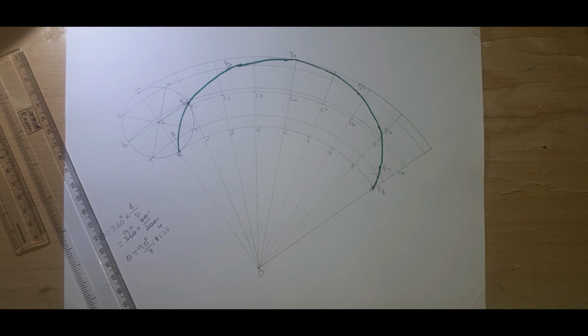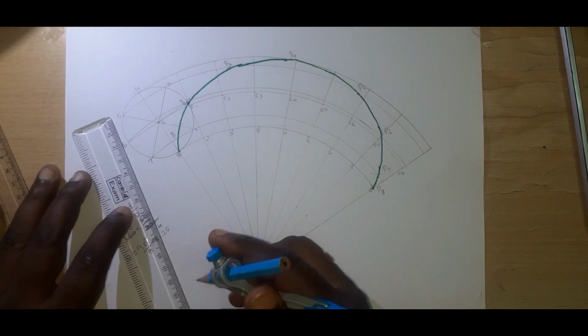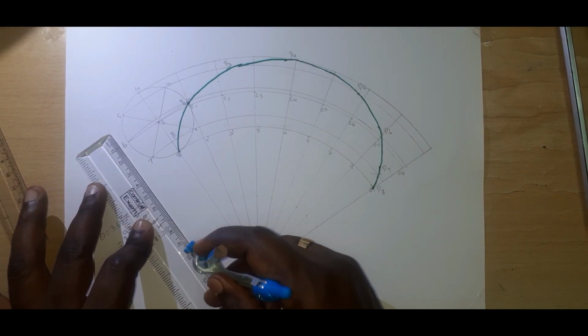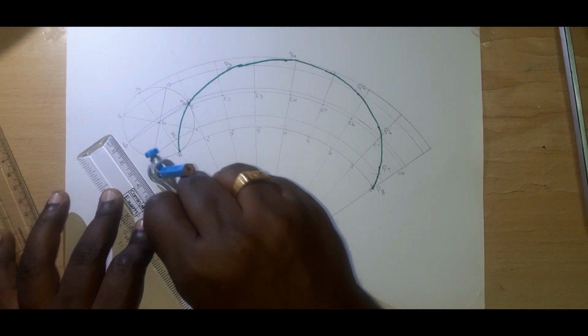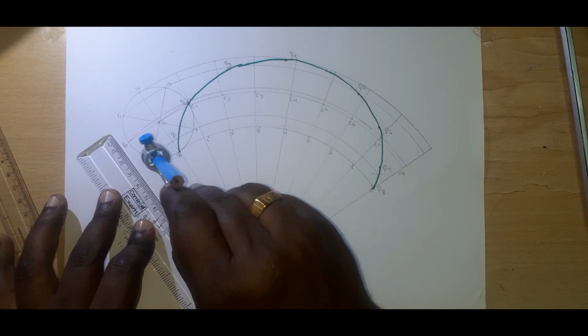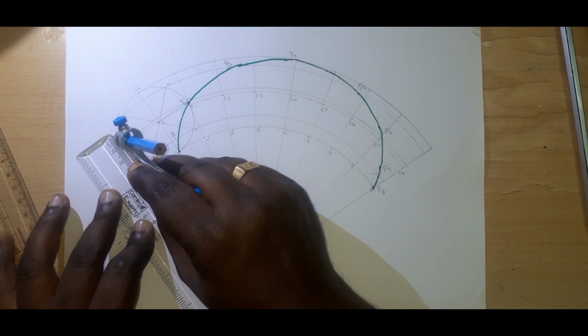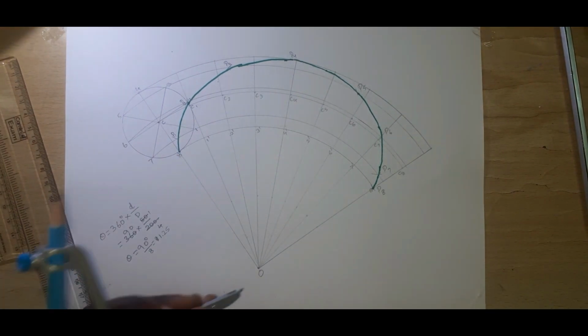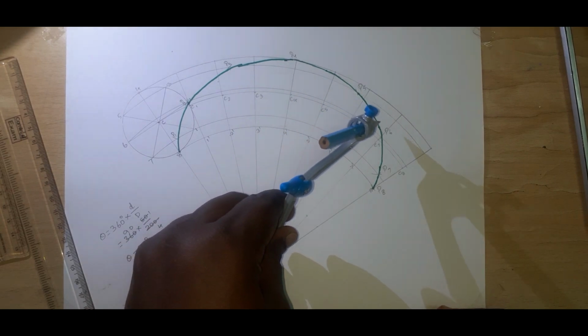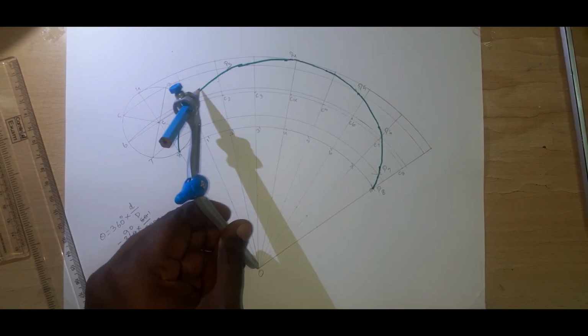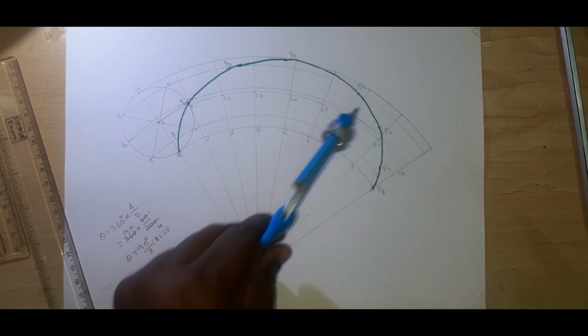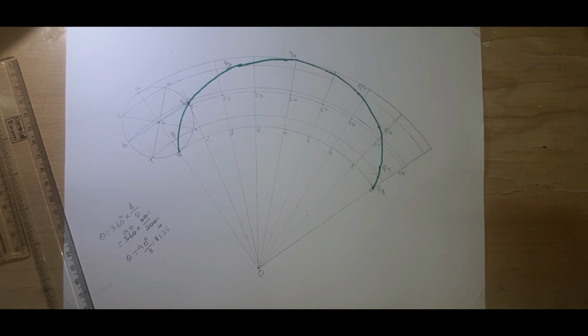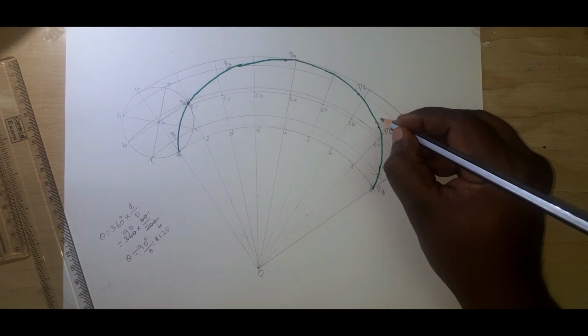And in your question it is told from the directing circle center. Which one is the directing circle center? This is the directing circle center. From here we need to take 135 mm. They have given the dimension, so we need to take the measurement on it. For 135, I am measuring a length. So this is 135. I am keeping this as a center. In your compass, take 135 mm, either this side or this side, any one side you can take. This side I am going to take. So here I made an arc. This is the point. The point is called P.